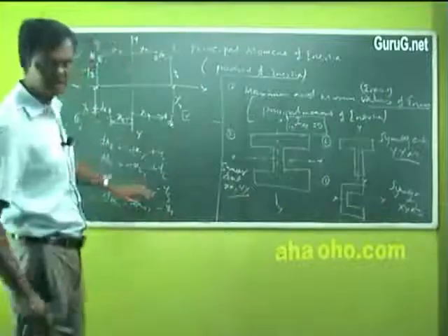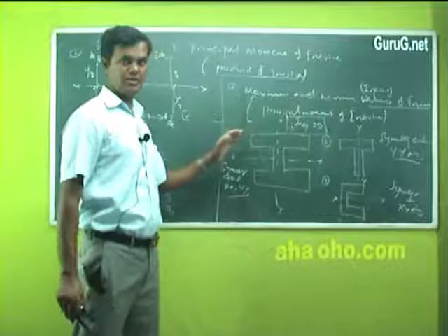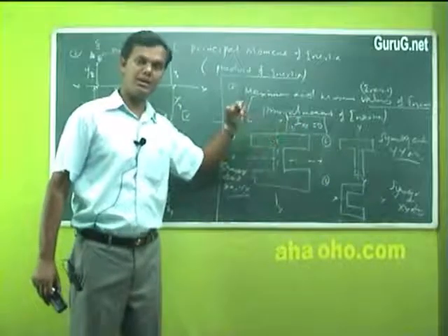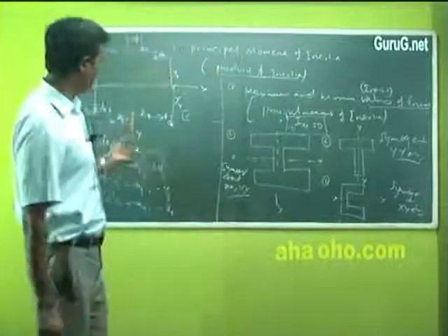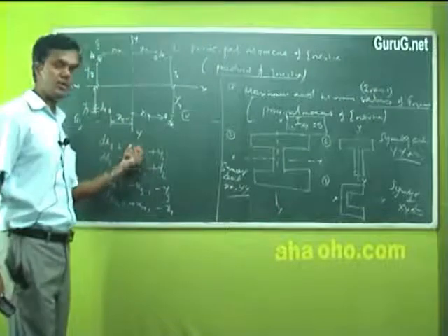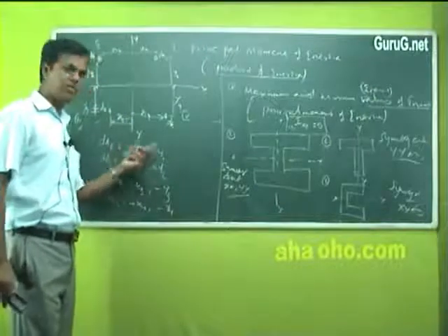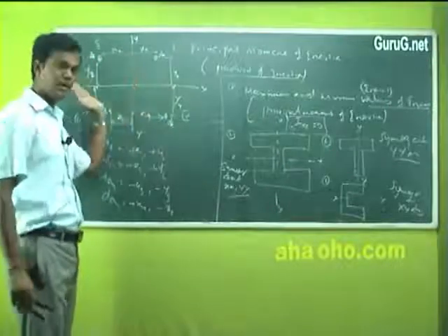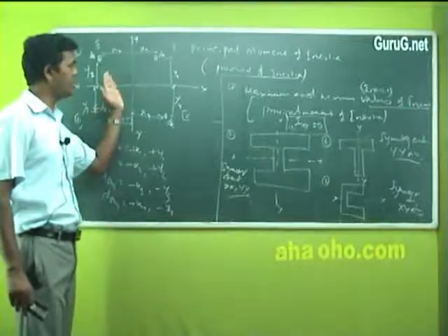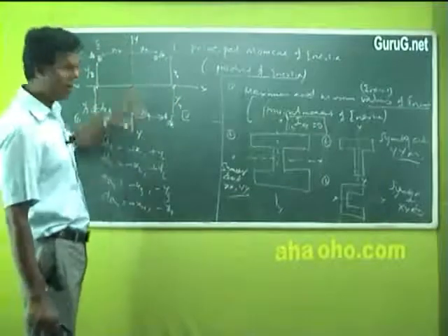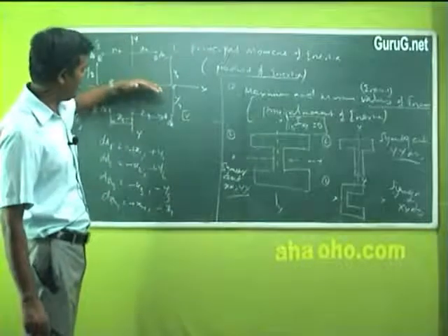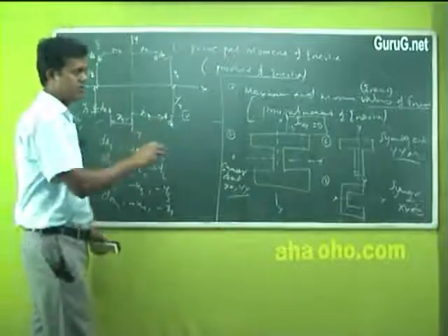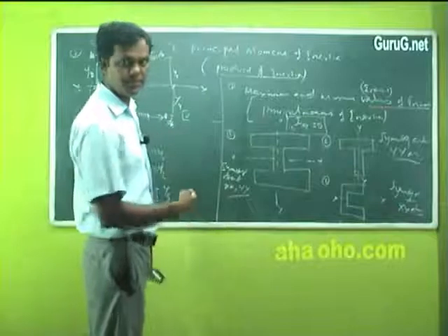So these conditions are very important, which means when we solve a question, for any sketch, the basic idea is if you have any symmetry either of x and y or to both the axes, you can directly write product of inertia is 0. The next thing is, using sign convention, we have to decide whether the value of that particular coordinate while calculating is positive or negative based on where it is situated. Right side to the y axis is positive, left of y axis is negative. I am talking about the x coordinates, because right and left is about x values, and above and down is of y, because you are traveling in the vertical direction. So above the x axis the y values are positive, below the x axis the y values are negative. Clear?